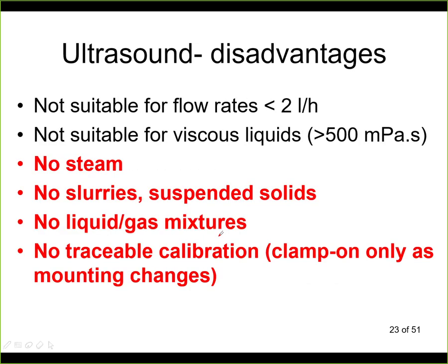Now disadvantages. It's not suitable for small flow rates. It's not very suitable for viscous liquids, so for example honey. It cannot measure steam because ultrasound will not propagate in steam, well, not in the way that we can detect that. And it cannot be used for suspensions. So if you have a mixture of a liquid and a gas, or liquid and solids, then it will not work.